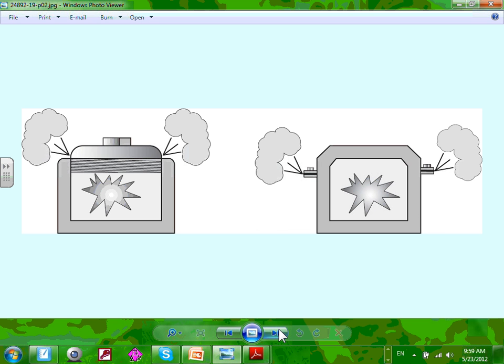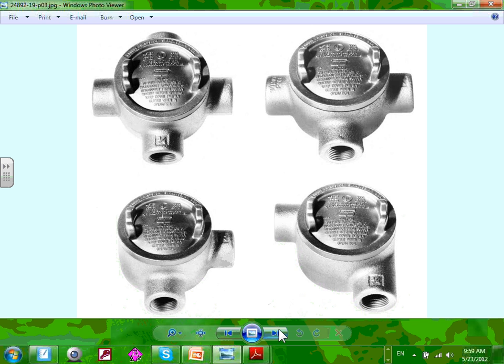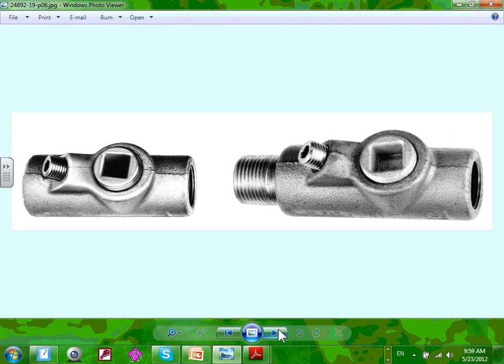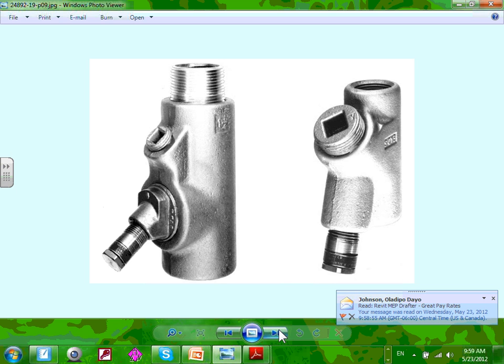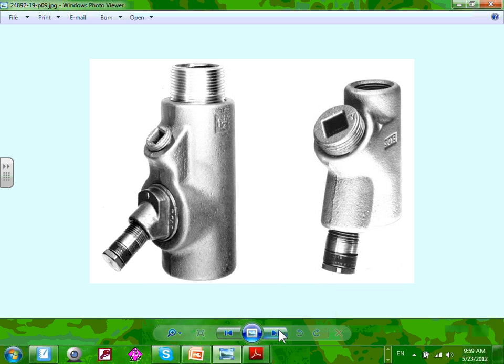Talk about the vents. Here's a couple of explosion-proof equipment, guys, with seals. The drainage. This is where you drain if you're putting it vertically, because of any condensation. You have to drain the system. This is a good example of a drainage, guys. So you seal this, the plug. You take this plug, you seal it right here, and this little deal here. Any condensation that turns into water in this pipe, because it can't go all the way, will go down through this and seep out. Either you have to unplug it, or some of them are the weeping ones. By design, every time it condenses, it just seeps through.